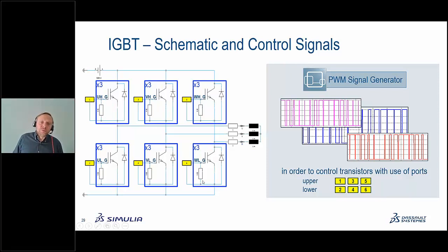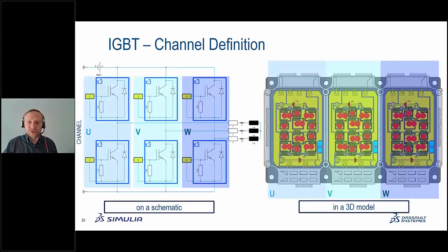And typically this will be driven by a PWM signal, which will be created by the controls. But as I said, we will not include the controls, simply because we are more looking now into the EMC things. We have such a macro inside CST Studio which can create arbitrary PWM signals, and they will be applied to the transistors we would like to simulate. And this section is currently, at this point in time, a very simple model of the motor. I will show you later on how we can also increase the accuracy of such motor models.